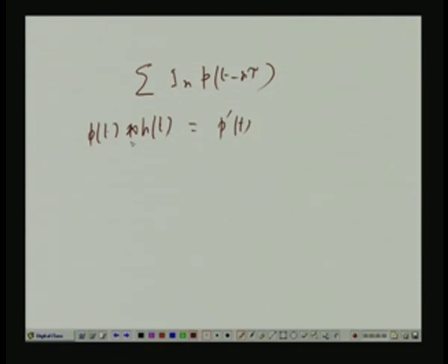So what you transmit is I[n] p(t minus n tau). The problem is that these pulses pass through the channel, and the channel is not ideal. So p(t) convolved with the channel will give rise to some p prime(t), and this p prime(t) will no longer satisfy the zero forcing condition. So what I will receive is, say, g(t) equal to the sum of I[n] p prime(t minus n tau).